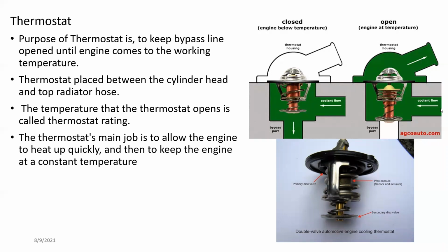The bypass valve actually closed, and the coolant flow started to flow through the thermostat valve into the radiator. This has a wax capsule inside. Once it has liquefied, this valve will be completely collapsed, closing the bypass valve. The wax capsule's actuating temperature is equal to the engine's operating temperature.